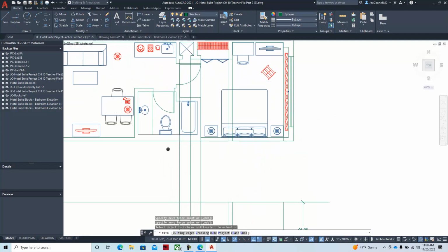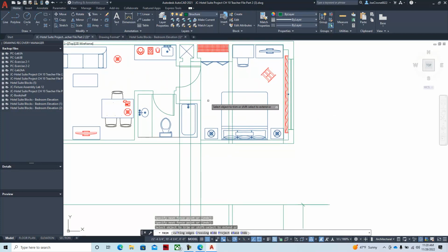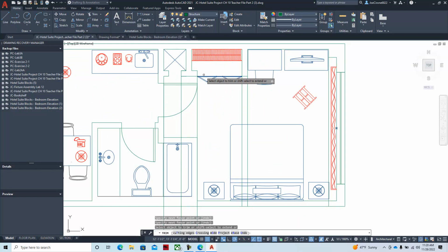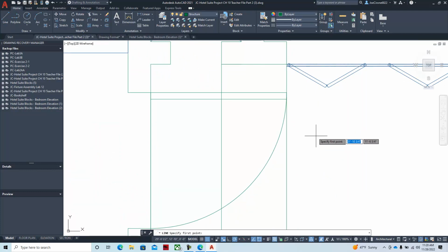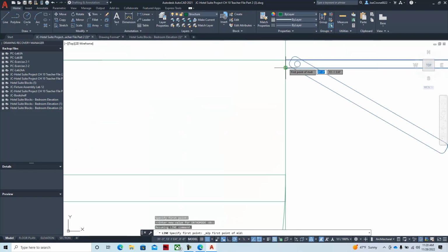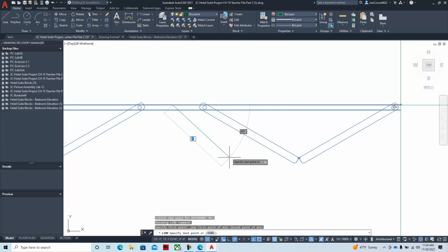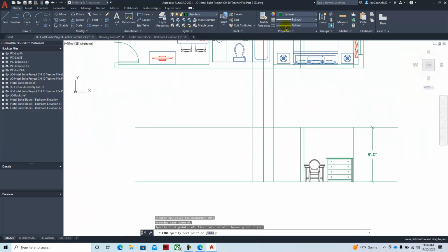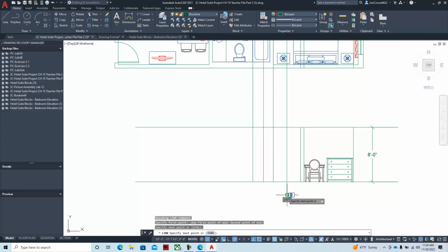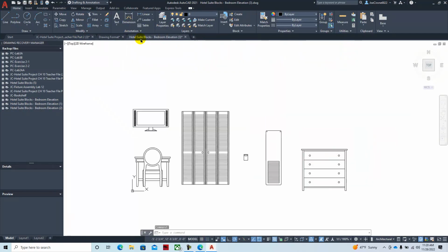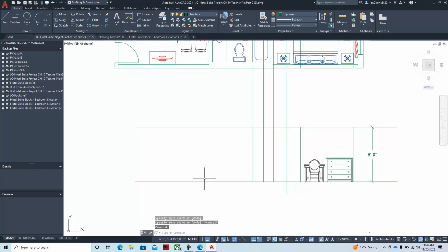And those 2 away. We'll put the doors on, and the way to get the center of the doors is to draw a line, midpoint between 2 points, between this point and that point. That'll give us the middle of our dresser doors or our closet doors. We'll get our blocks, Control C, Control V.